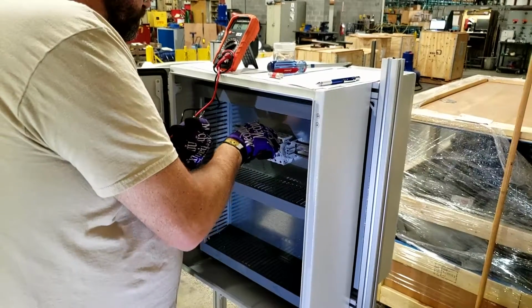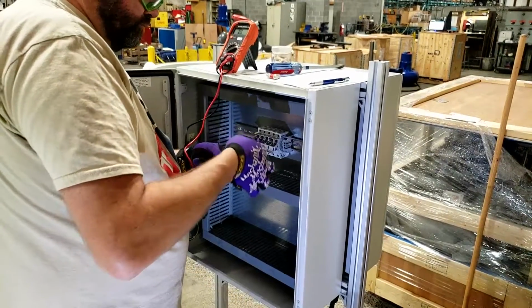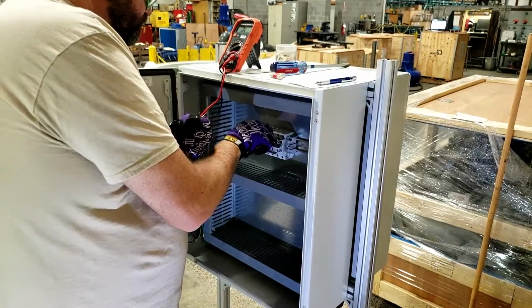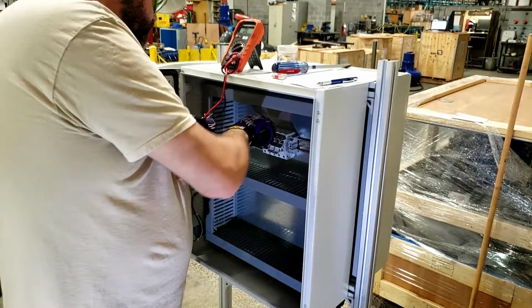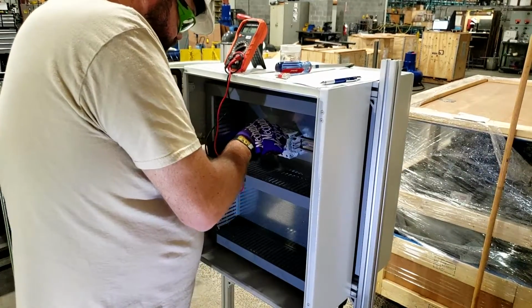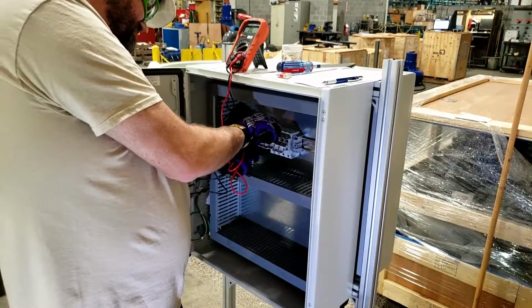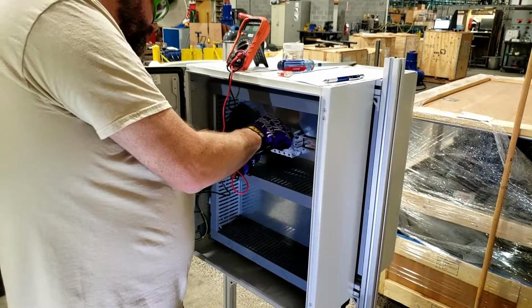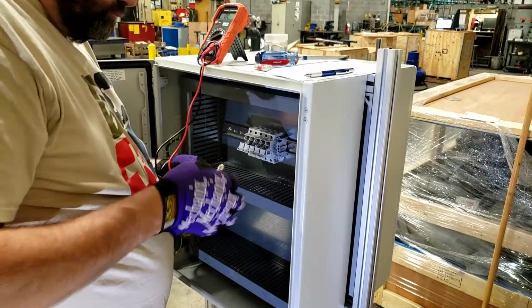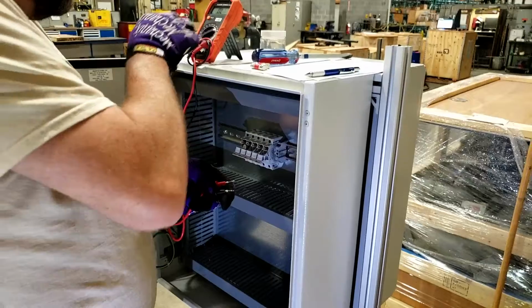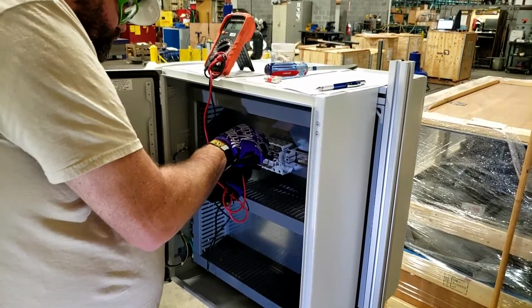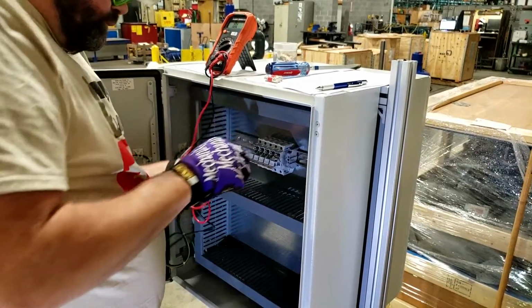You will then reinstall only good fuses by putting the button in first. You will replace any bad fuses with new good working fuses. You must check any replacement fuses for continuity as well to ensure they are good prior to installing. Once you have installed all 5 good fuses, you will then close the breakers for each fuse.